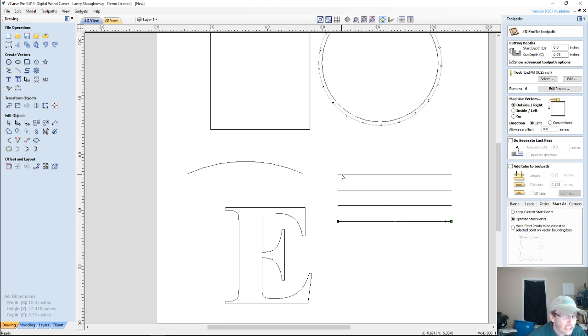But if I intentionally want, when it cuts this line, to raise up, come back, and cut this line again, because I want to cut in a certain direction across the grain, or I want to reduce tear out in MDF, if I'm going back and forth I could be getting tear out where I don't want it.